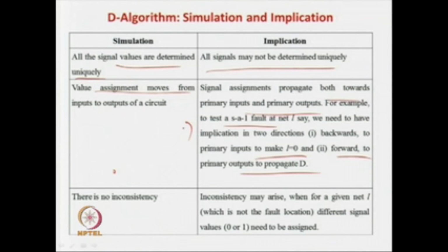That is what it is actually saying, that if you have an AND gate, and this one is actually stuck at 1, then you apply a 0 over here. This is the forward direction, you can say, because we can consider this to be the D frontier, so it will actually be D prime in this case, because normal case 0, fault case 1, stuck at 1.